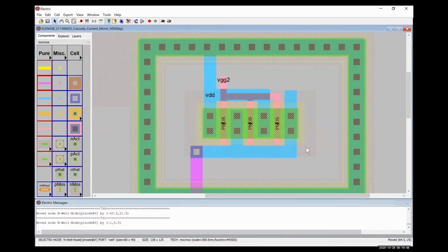So if I put this in, this whole big box is then N-well, and by putting that 5 volt potential on my guard ring, I'm saying this whole big thing will be at exactly 5 volts to avoid body effects. Did that answer your question? Yeah, that makes a lot of sense. Thank you so much. Yep.